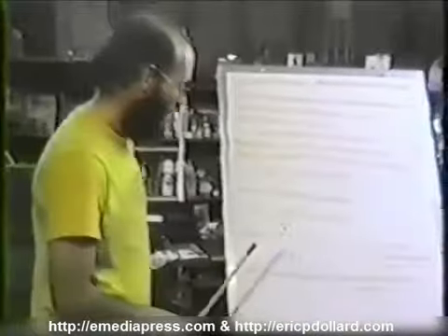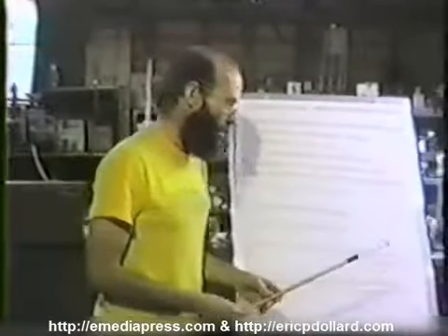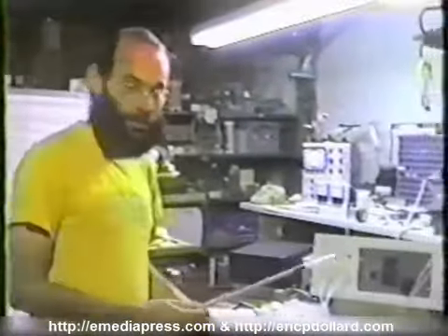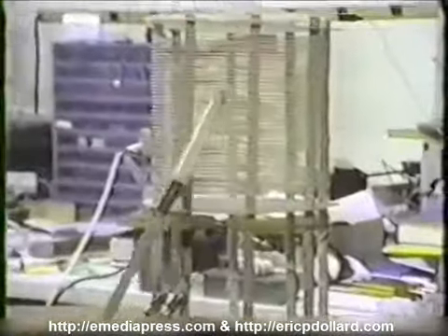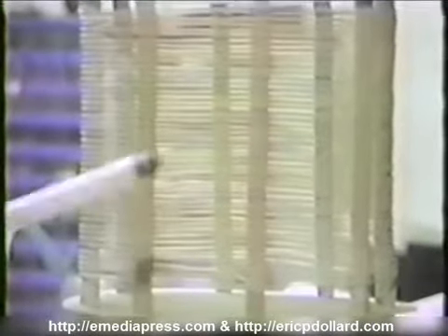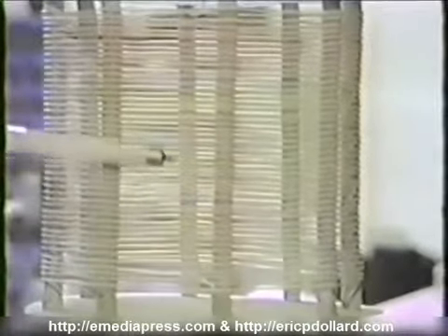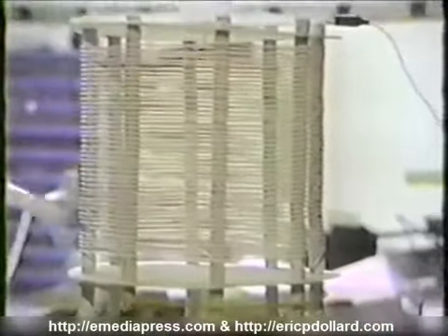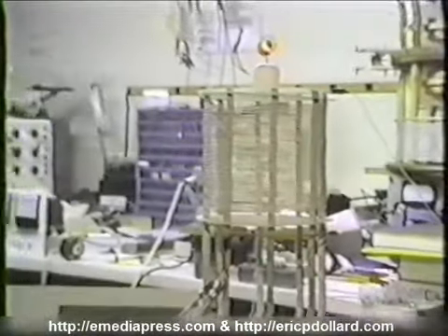So we've broken the speed limit of the velocity of light. Or you might say we might get a ticket from the relativity police in this case. At any rate, going back to our structure over here, we can see how this occurred. We're really not having transverse flow between the turns anymore, but the energy is now spiraling due to the complex quantities of induction along the wires in this direction. So we have a spiraling wave around the coil, and this gives us an effective velocity exceeding that of the